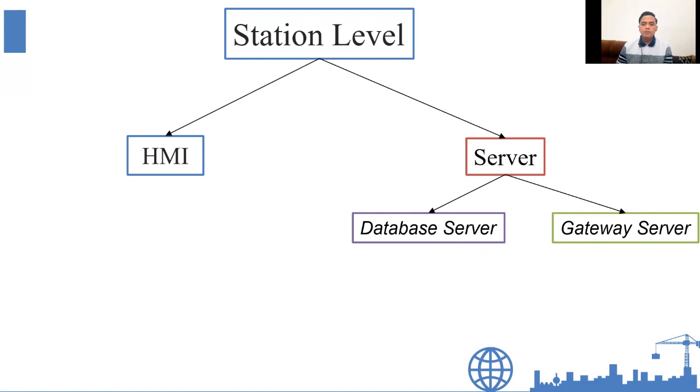The main purpose of this machine is to perform as a protocol converter between IEC 61850 and various other protocols used in the substation to the protocol utilized in the master station, primarily IEC 60870-5-101 and IEC 60870-5-104.